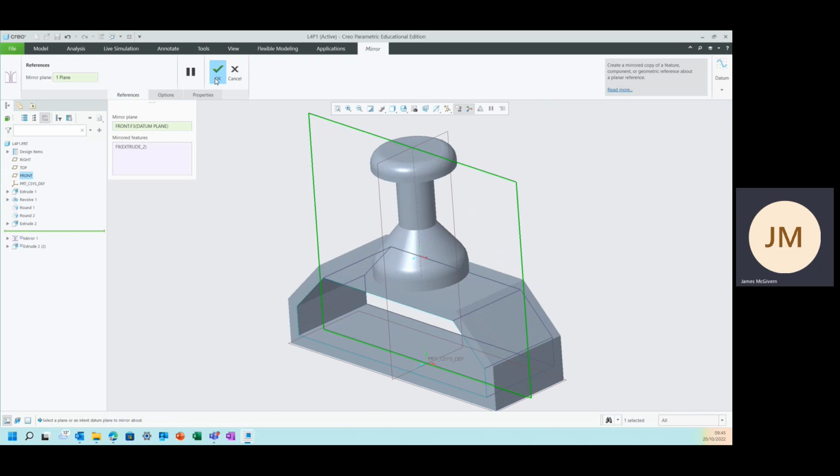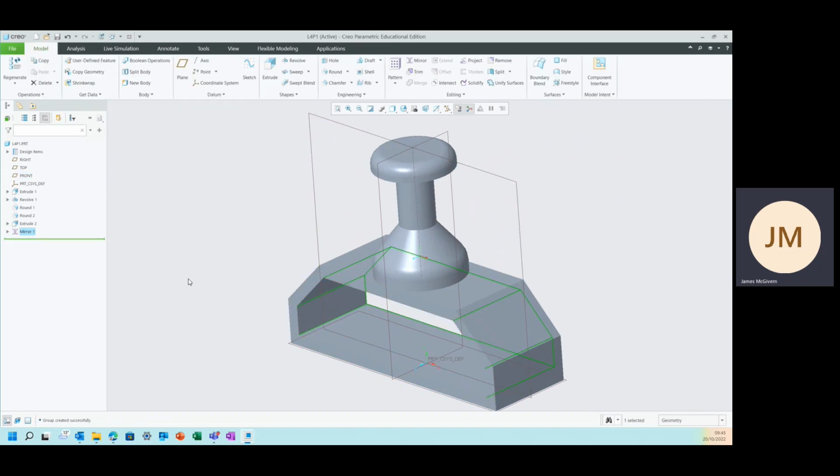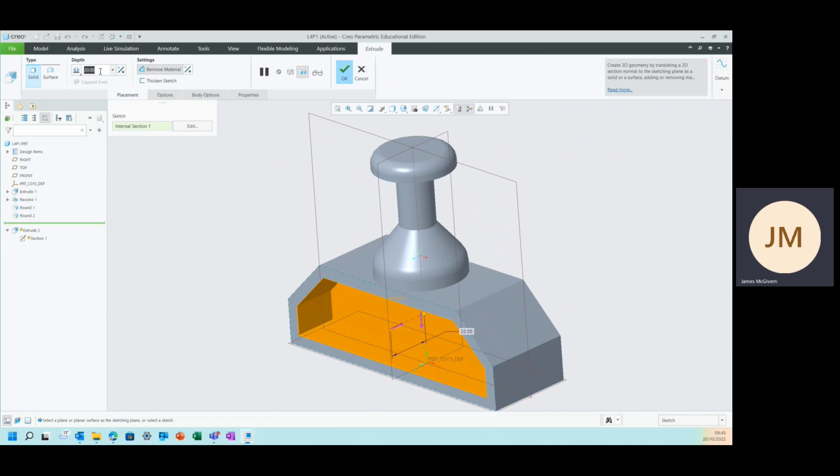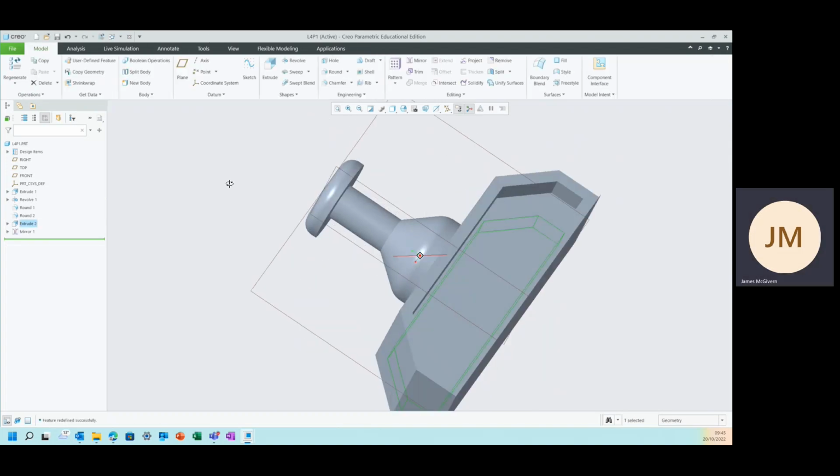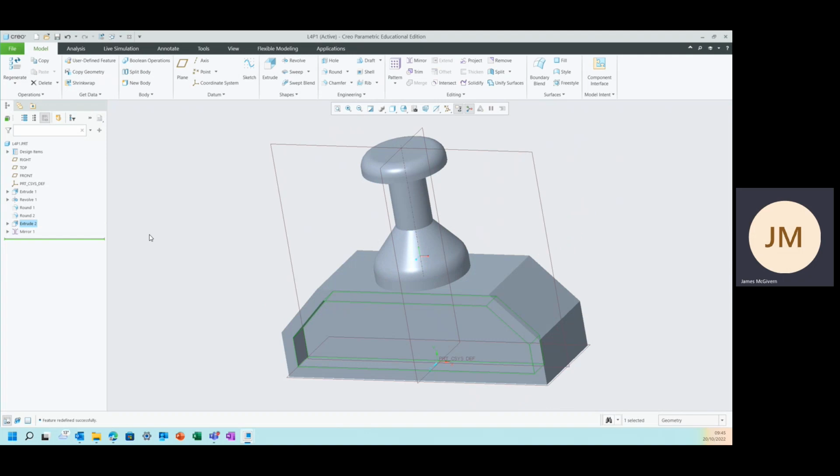Now I'm going to have to go back in and reduce the size of that extrusion because it left me with no wall. So the extrusion itself I want to adjust. It's 20. So if I make it 10, both of them are changed at the same time. Both of them are now 10. So that's showing you how to edit it.